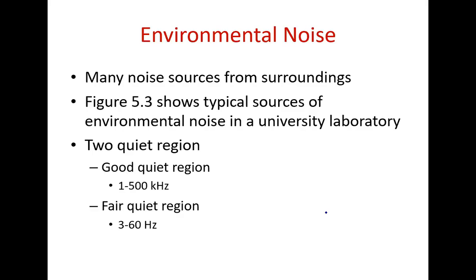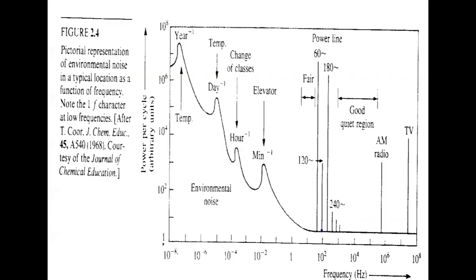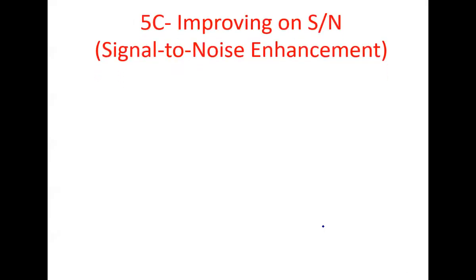And in the region of slightly higher frequencies, 10 to the 4th, 10 to the 6th, you usually get a spike, very narrow band. Unlike low frequencies, there's a continuum, and the noise is riding on the flicker noise. So that brings us to that.